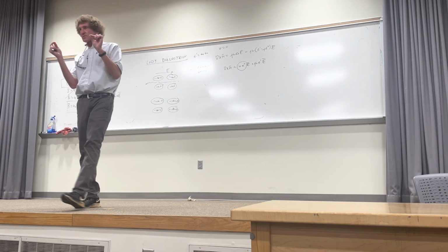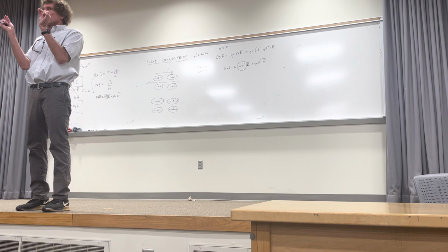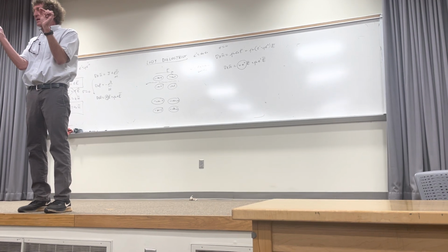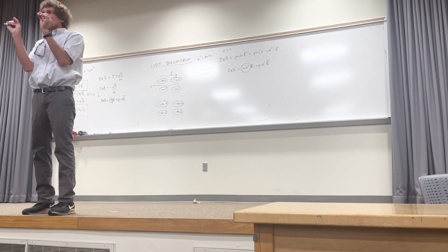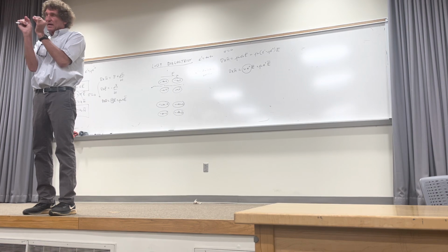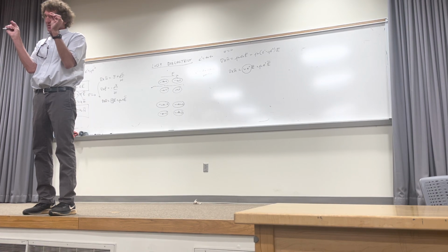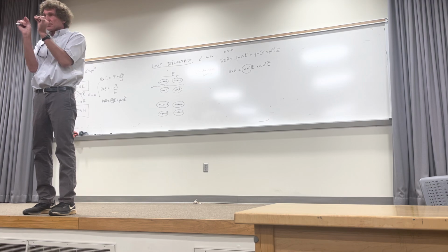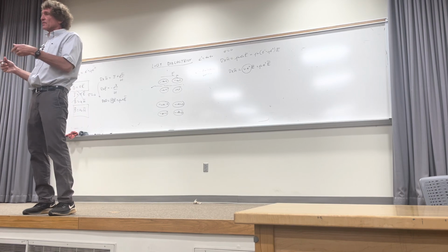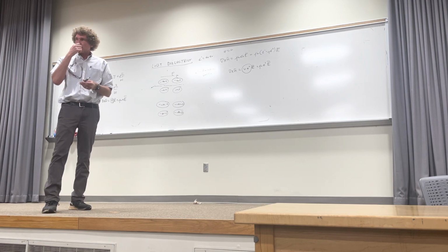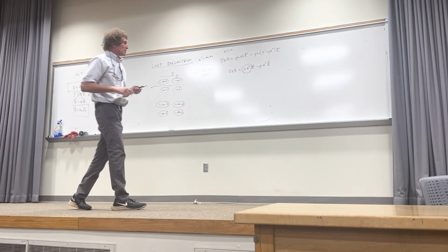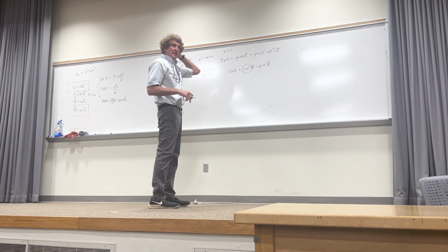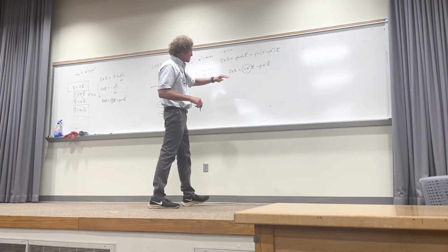For a given electric field strength, every time you go through a cycle and you flip the polarity, those molecules contract and then they are compressed in a sense, then stretched back out apart. You all follow me? If they're aligned, that causes a frictional heating. The amount of frictional heating that occurs is proportional to the number of times that happens, and that means it's proportional to frequency. Higher the frequency, more times it happens per second. Does this make sense, everyone? And this is a general rule. So this is the way we deal with dielectric losses right here.